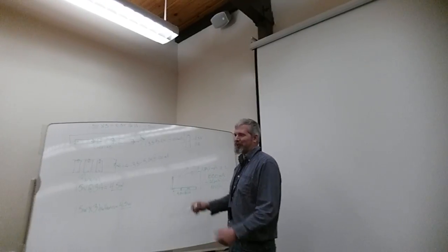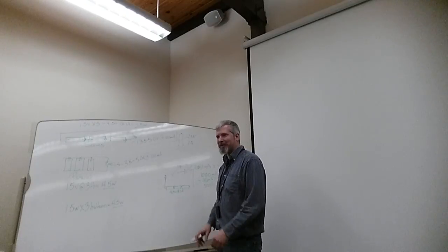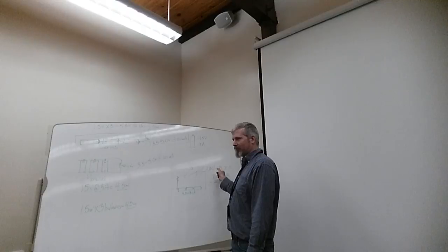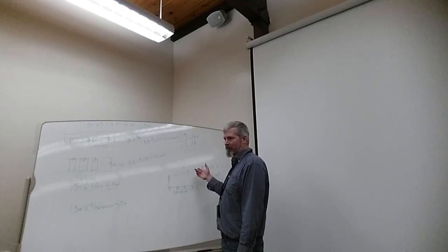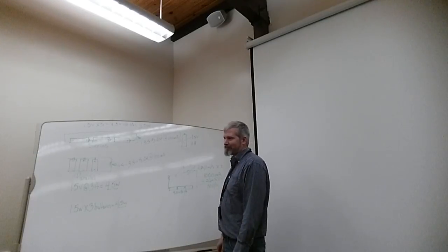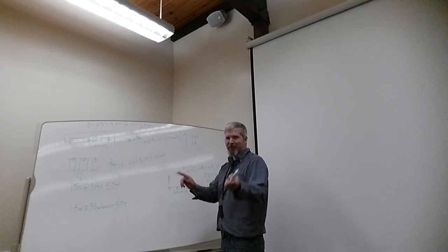There we go. We shorthand when we were talking, so that's what actually happened. They were 2.25 volts times 2, because they're in series, would be 4.5 volts. They both run a milliamp, so they're running 2 times 1 milliamp to make 500 hours. Okay. Yeah. Good catch on both sides.